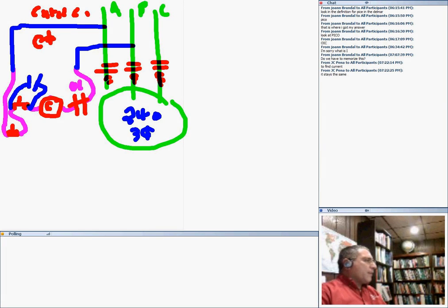If you haven't done much of this, ignore what I've just said. The contact is called the holding contact. You hold it in parallel so you can hold the circuit shut after you push the start button, because the start button is momentary. Great application in control for a series circuit.